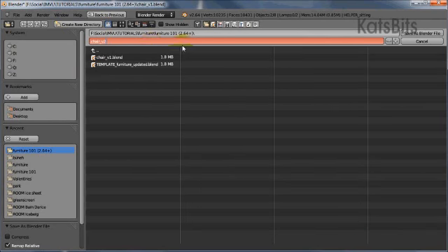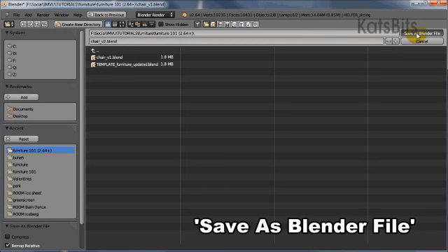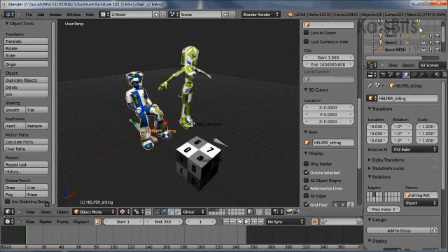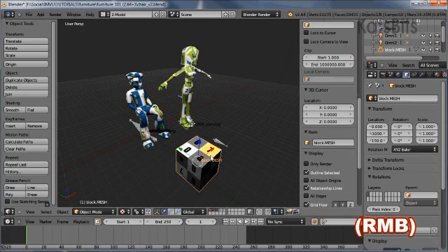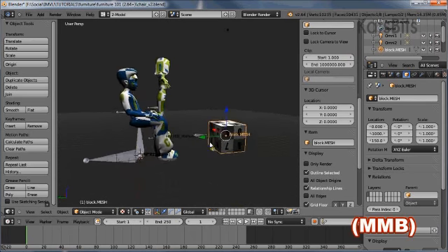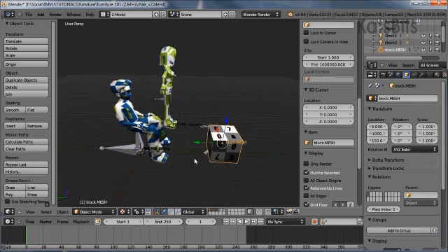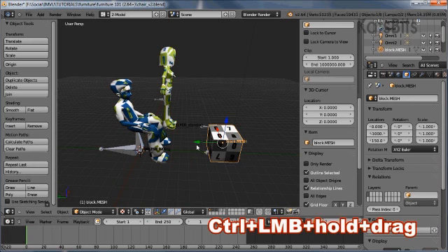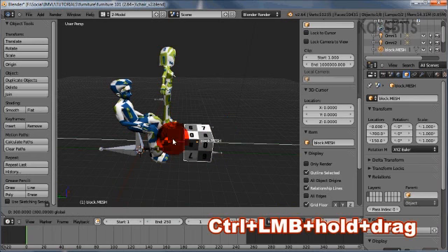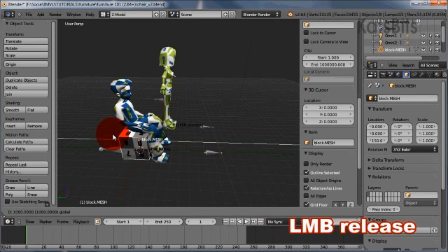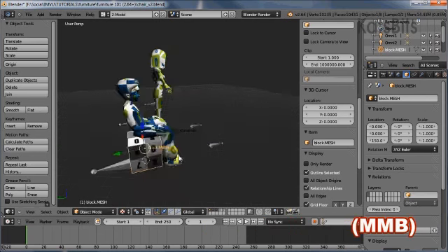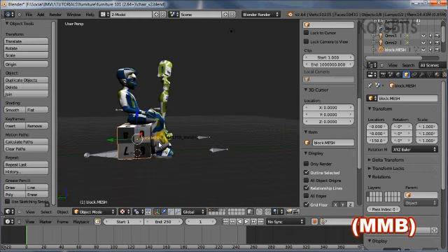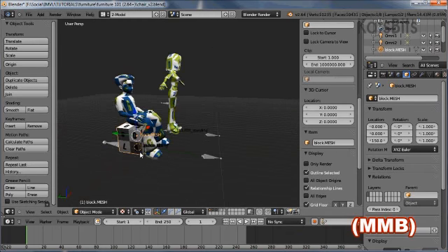version 2, enter, and then click save as. Next we want to move the mesh into position so that it's seated underneath the armature helper. So as with the seating helper and the armature, left click hold drag with the control key down and move that so that it's underneath the seated avatar. Release, and that's the basic position of the chair sorted out.